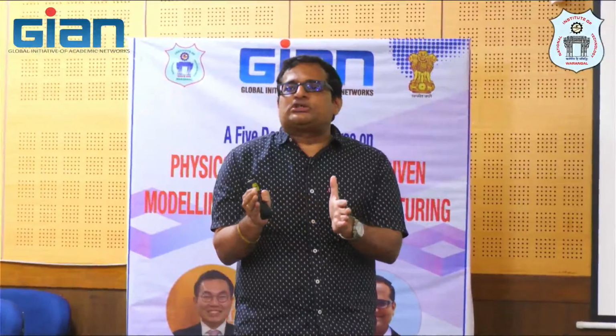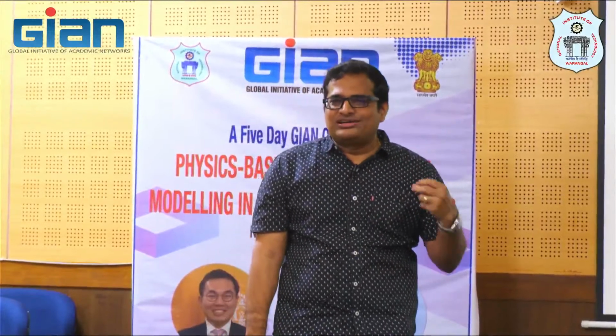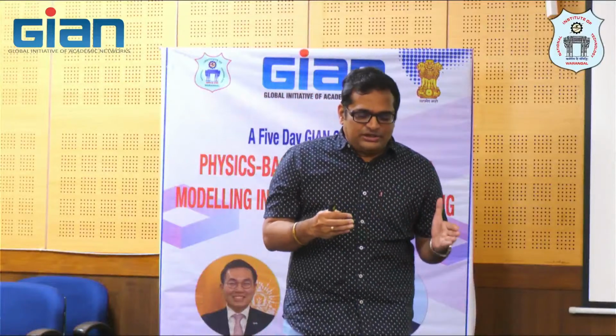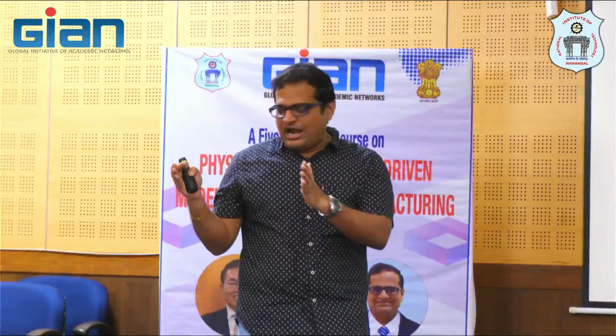See, yes, you approach the machine vendor. The machine vendor says that yes, titanium 64 is biocompatible, which FDA has approved. You can use it absolutely as a material. Yes, absolutely, it is FDA certified. It's a biocompatible alloy, you can make use of it. But the challenge here is, at the moment you process it in an AM machine, you are melting it, and you are doing some sort of autoclave, some sort of sterilization. And again, we need to follow some FDA guidelines for that.